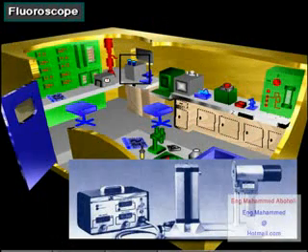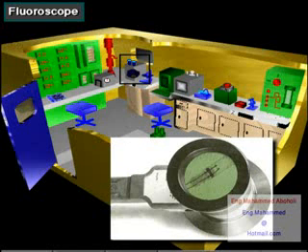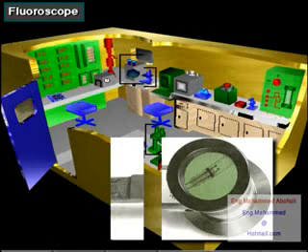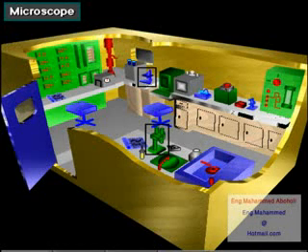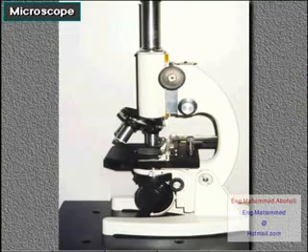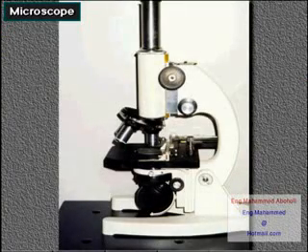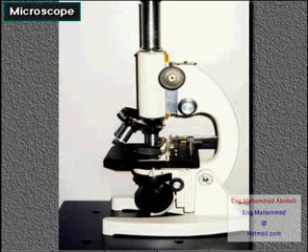A fluoroscope contains an ultraviolet lamp. When the mud logger or geologist puts cuttings or a plug under the fluoroscope, the cuttings or plug glow, or fluoresce, if they contain hydrocarbons. A microscope, this unit has two, helps the mud logger or geologist identify formations. By looking at cuttings or plugs under the microscope, the loggers can note very small rock characteristics. They may also find fossils that help identify the rock.